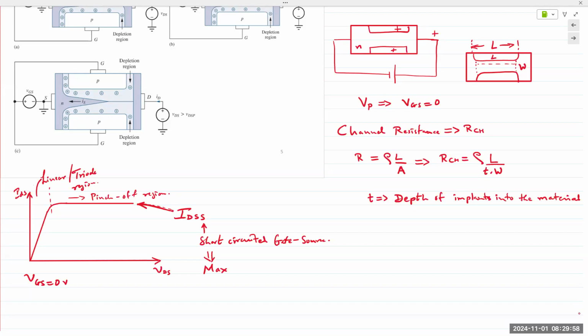Within those limits, yes, it'll work. Again, as I said, every JFET will have a maximum IDSS, and depending on an application, we can choose that. But you make a very good point, because the whole purpose of using transistors, FETs, BJTs, MOSFETs, is because we can control it with a third terminal.